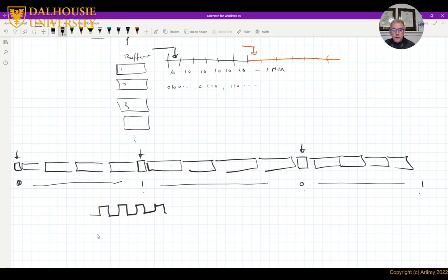If for some reason it sees 0, 1, 0, 1 and then 0, 0, right? It means that it lost sync, because it's expecting 0, 1, 0, 1, 0, 1. So it's not receiving that anymore. There must be a lost sync. In that case, the demultiplexer has to take action. Maybe it discards some of the data and starts to go back and try to resync again, right?